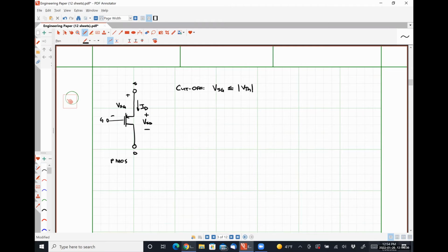So we're going to be stuck with a bunch of absolute value signs here. In practice, if you just read the threshold voltage for a PMOS transistor as a positive quantity, you can throw away all these absolute value signs. They mean next to nothing. We're just working on the understanding that the gate needs to be lower potential than the source in order to turn this guy on.